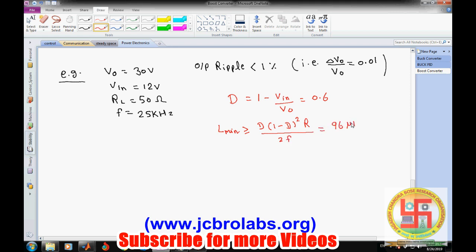And then we can identify the value of C. C should be greater than this value, which is given by D divided by R into del V out over V out, which is the ripple, into F, and it comes out to be 48 microfarad. So if C is a minimum of 48 microfarad, then we will get the ripple of 1%.